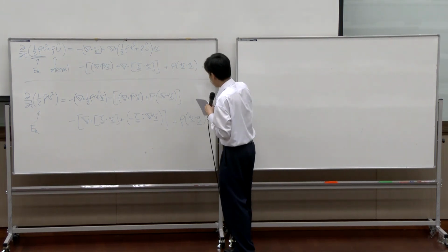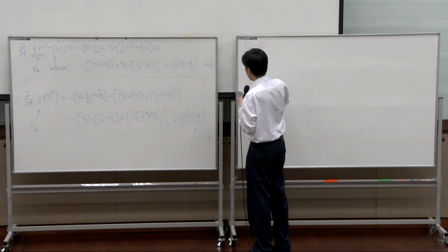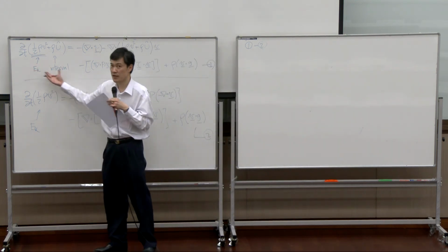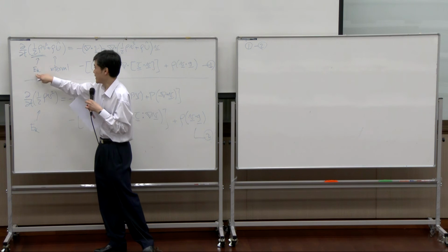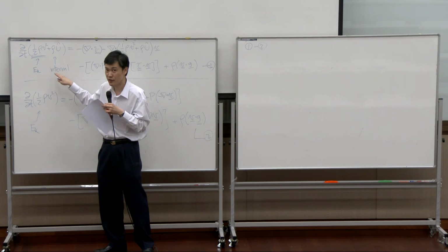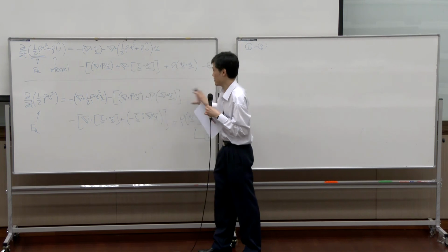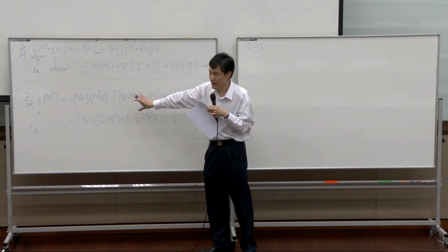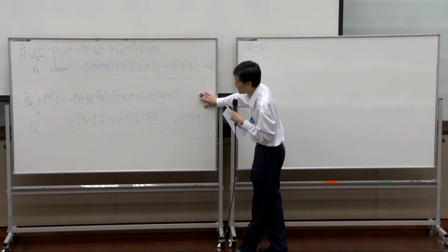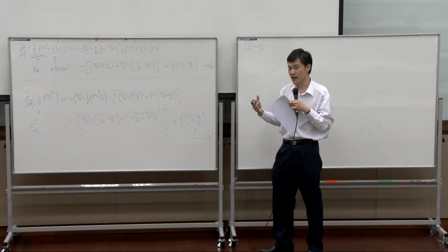If this is called equation 1, and this is called equation 2, taking equation 1 subtracted by equation 2, what do we get? Just look at the accumulation term. It would be easier. You have kinetic and internal subtracted by kinetics. So you end up with internal energy change, right? So basically, equation 1 is overall energy. Equation 2 is kinetic energy only. So when you subtract kinetic energy only from overall energy, you end up with equation representing internal energy.